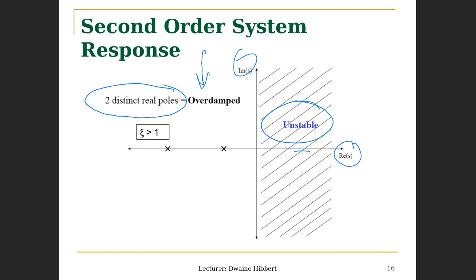Equivalently, we're saying the damping ratio, the damping constant, is greater than 1. The damping constant is that factor that tells us how much damping is in a system. What we're going to recognize is that depending on the number, we'll see the system behaving in different ways. So once you have damping greater than 1, we say the system is over damped, and in a short while, we'll see what an overdamped system response looks like.